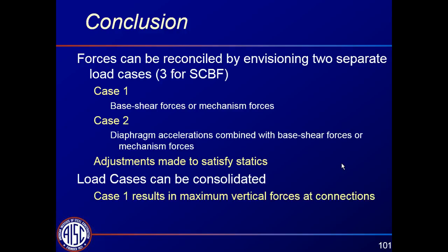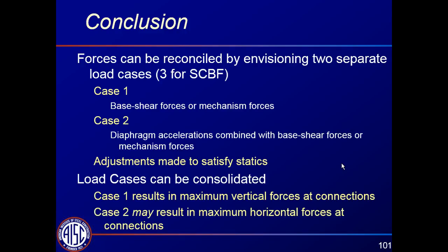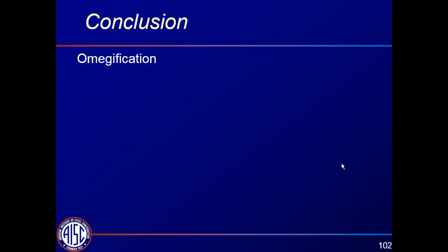Typically, case 1 is going to result in the maximum vertical forces at the connections, and typically case 2 will result in the maximum horizontal forces, unless of course there's a case 3, in which case 3 typically gives you the maximum horizontal forces.